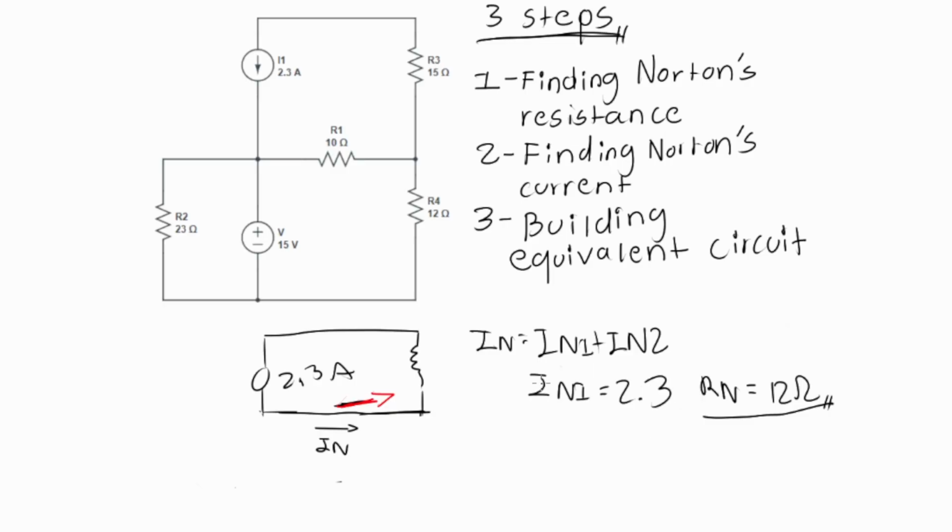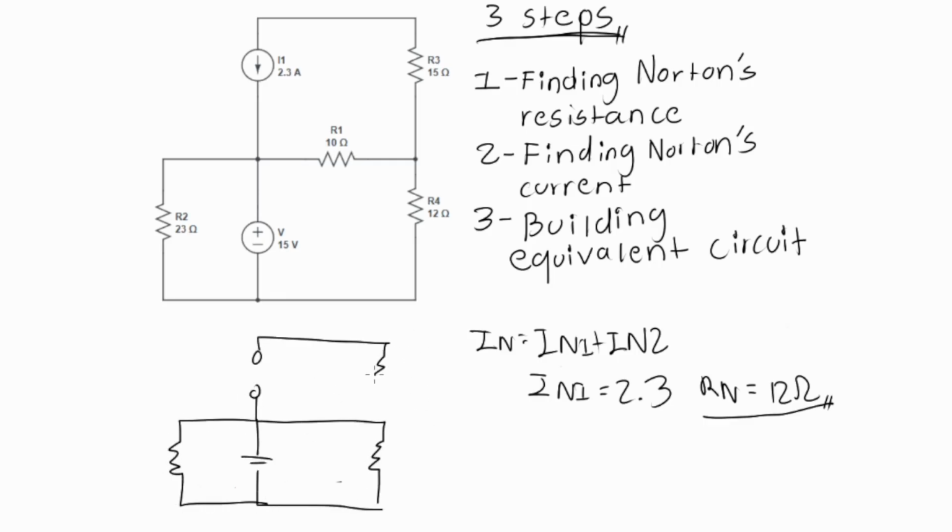It's that easy. Now let's analyze the circuit with just the voltage source active. As you can see, we open the terminals of the current source, as I told you. And because of that, no current and no voltage will flow through resistor 3, because this is open. So no current will flow through there, so we can get rid of the resistor.